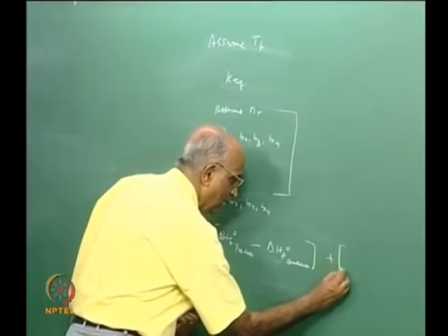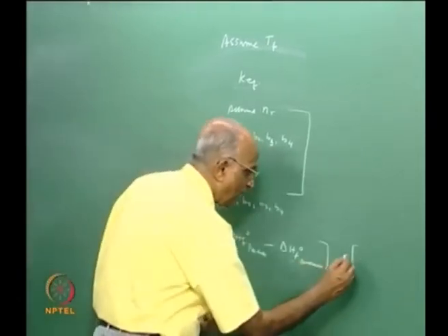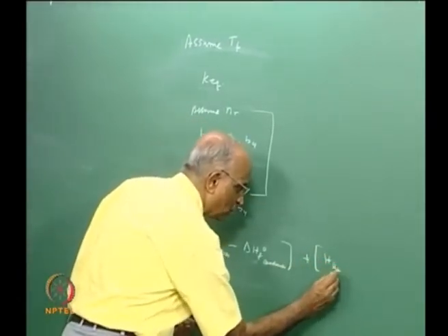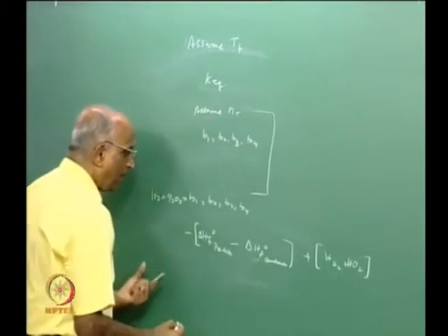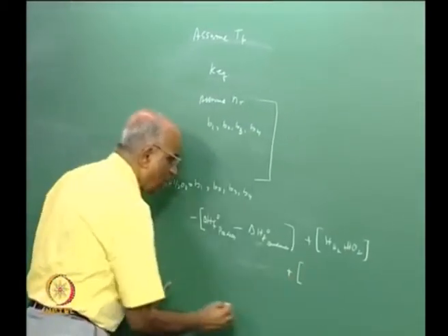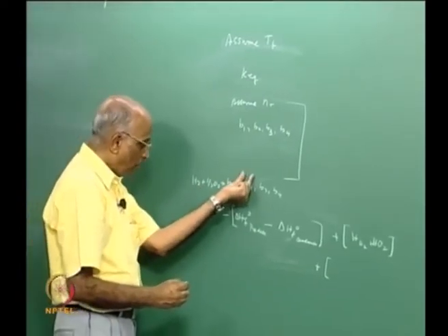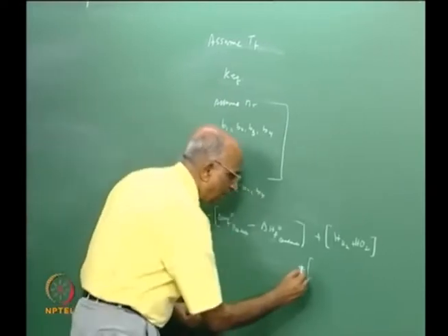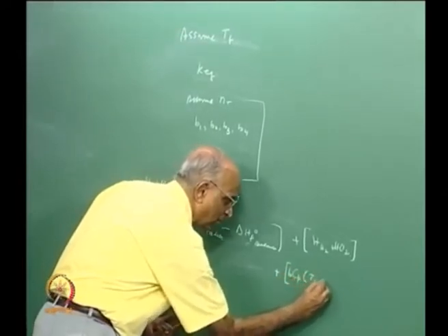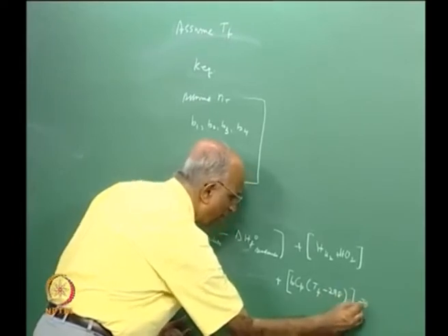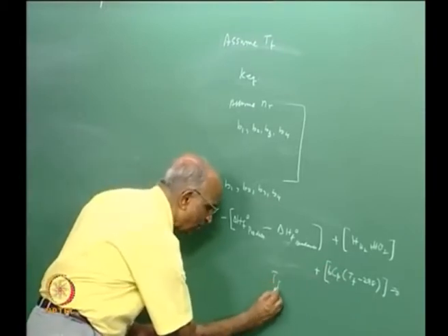That means I say I have the liquid phase, I have the latent heat phase, I have the vapor phase. Therefore, I have the heat required for H2, that is one of the fuel. Similarly, I have for the oxygen what is the enthalpy required, and again what happens is the balance of heat goes into sensible heat for the products and also latent heat as applicable for H2O, which I do not explicitly write. And this must be 0, right? This goes into this and to raise the temperature. Therefore, I get the new value of temperature.